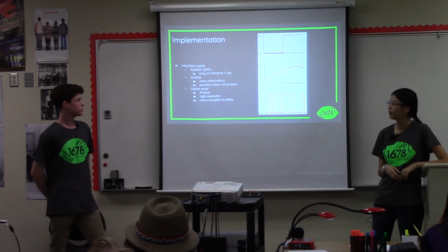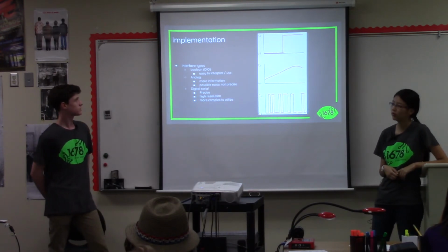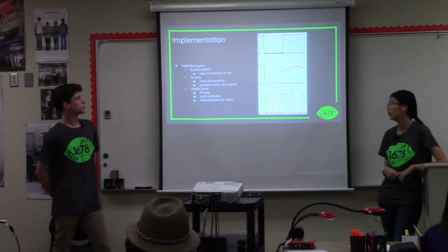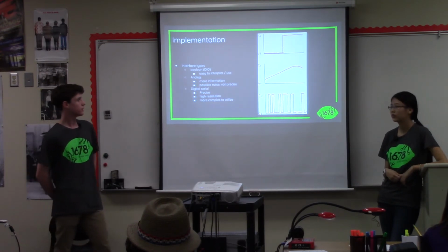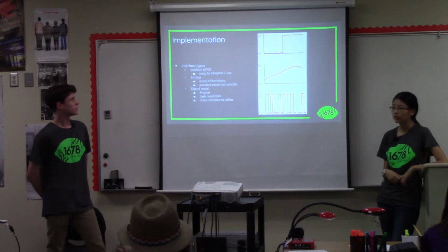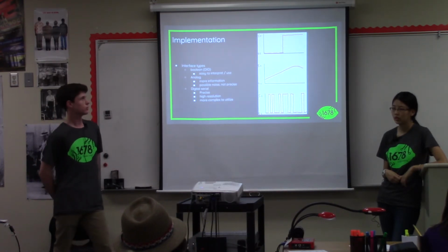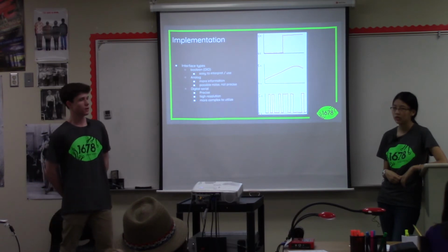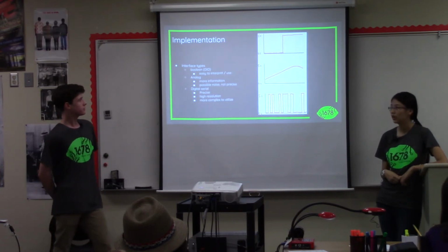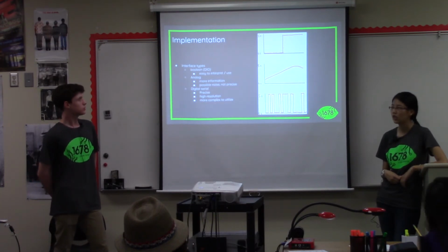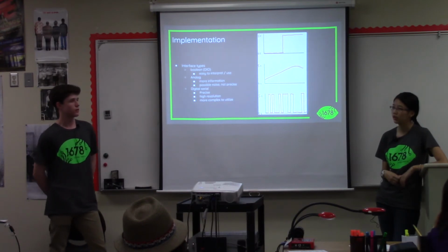Sensors can give out different signal types, like Boolean, analog, and digital. The first graph in the diagram is a Boolean signal, where it's true or false, so it's either 5 volts or 0. This type of signal is easy to interpret, but it has limited use because it's only one output.